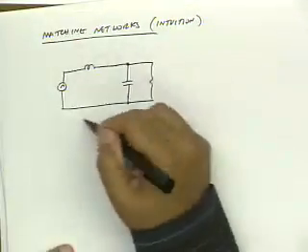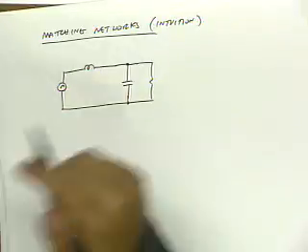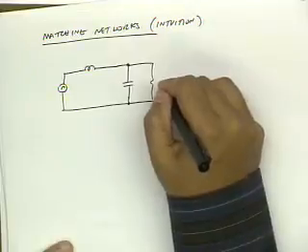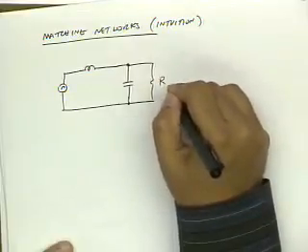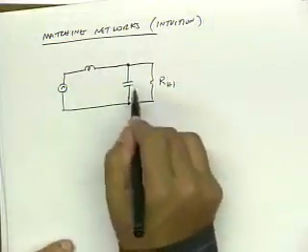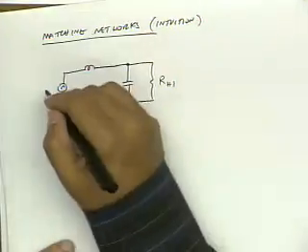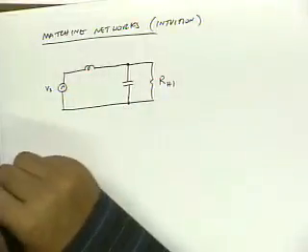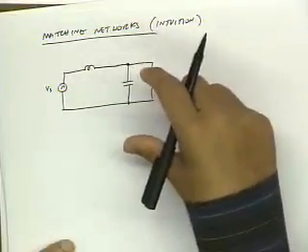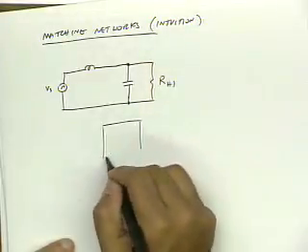Let me make sure I've got the intuition right before I try to give it to you guys. So this is R high, and this L matching network is going to transform this to R low. So what I'd like to do is take this voltage source and somehow boost the voltage that drives this RL. In other words, if I go back to my picture of a transformer,